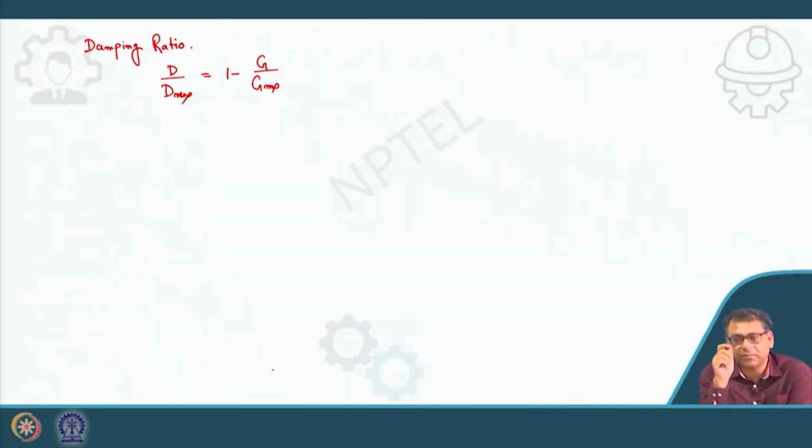So that means that for low strain condition, your shear modulus is maximum, and as strain increases, the shear modulus value decreases. But damping is opposite: at the low strain level, the damping is lowest. As the strain level increases, your damping value will also increase. Clear? I will show you the trend. My equation is also showing that.